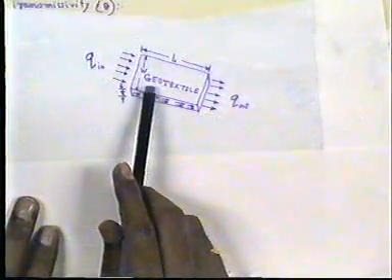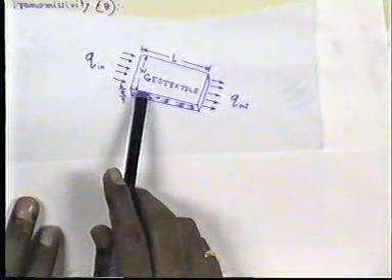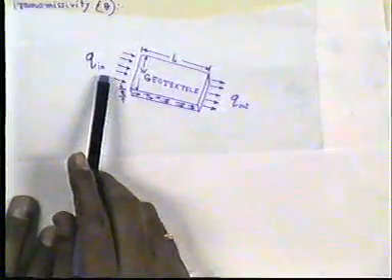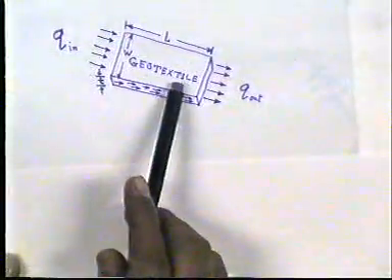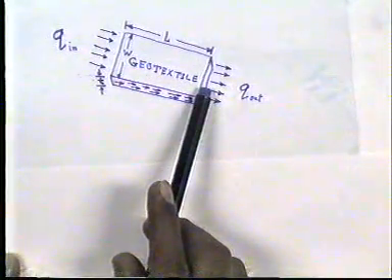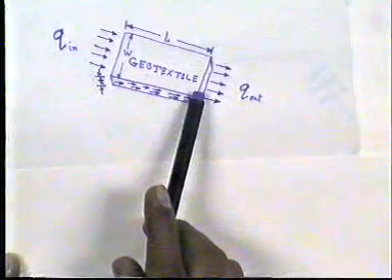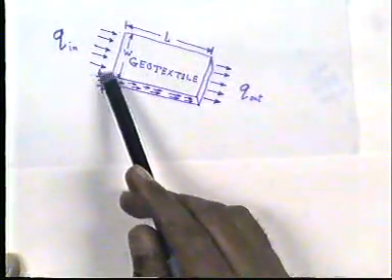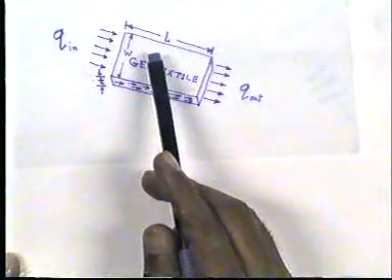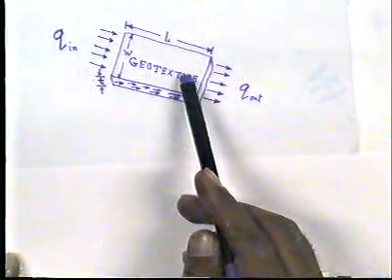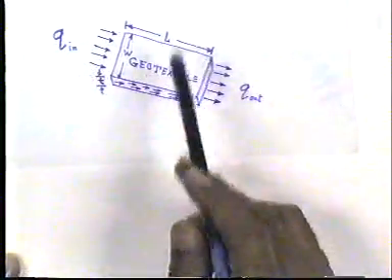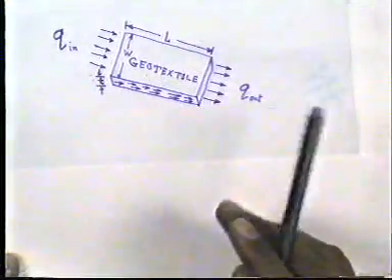The amount of water that will flow along the plane of the geotextile material is dependent on the thickness of the fabric, the permeability of the geotextile material, and the overburden pressure.